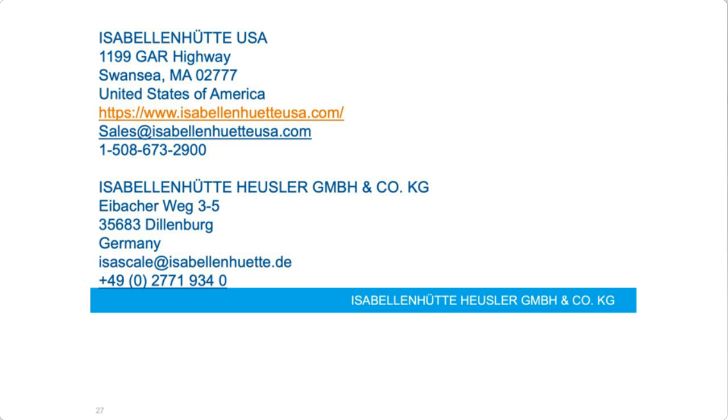The temperature compensation is over lifetime, and we rate our IVT 3.0 product for 0.1% initial accuracy. What does initial accuracy mean? Initial accuracy means that we make sure with our end-of-line quality control that no product leaves our factory with an accuracy worse than 0.1% of reading.